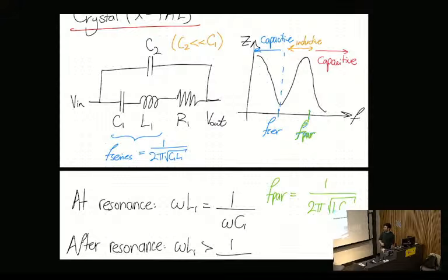Okay. Now, what's important for the question especially is that we put load capacitances here to vary the value of these resonances. So we can vary where these resonances are, depending on whether we're using the series or parallel one, just with these capacitors.